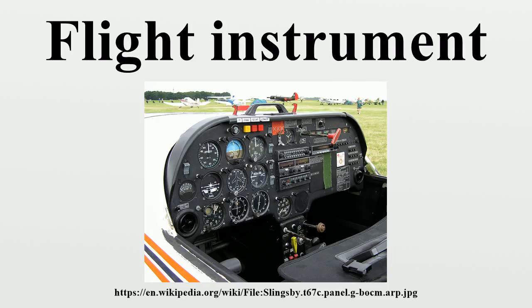But the other 5 flight instruments, sometimes known as the Big Five, are still included in all cockpits. The way of displaying them has changed over time, though. In glass cockpits, the flight instruments are shown on monitors, but the display is not shown by numbers, but as images of analog instruments. The artificial horizon is given a central place in the monitor, with a heading indicated just below.